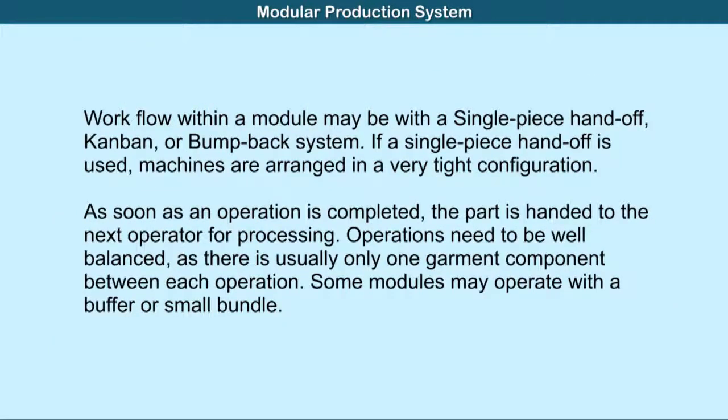Workflow within a modular system may be with a single piece handoff, Kanban, or bump back system. If a single piece handoff is used, machines are arranged in a very tight configuration. As soon as the operation is completed, the part is handed over to the next operator for processing.